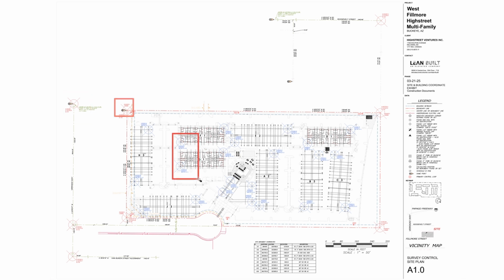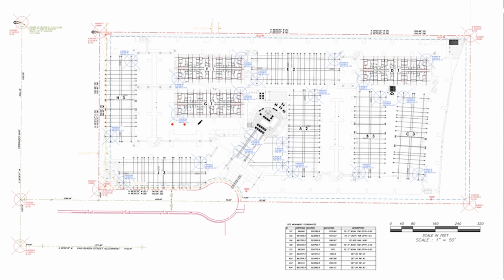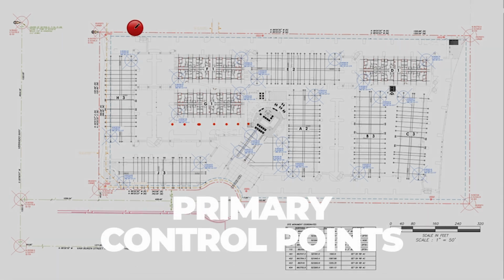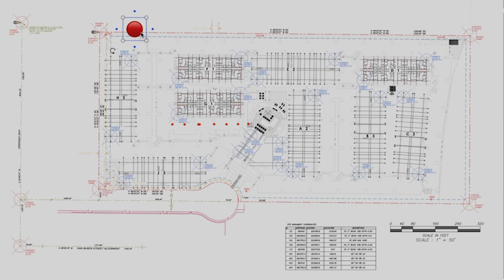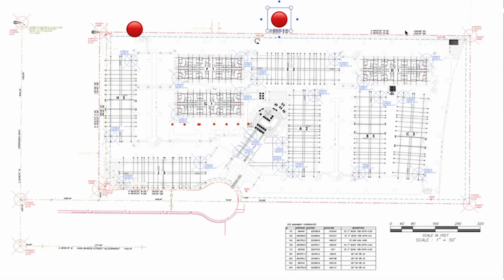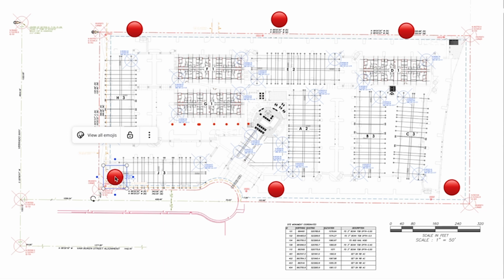Now, what we're going to do is sign up the surveyor to establish secondary control points. So let me come over here and draw that just a little bit. Let's take building 1. We'll probably create a baseline along the side here that is based off of grid line intersections. And this is very similar to what I talked to you about last time. We will create primary control points. The last time I spoke with the surveyor, I generally roughed out that we would have primary control points generally in these locations around the project site.